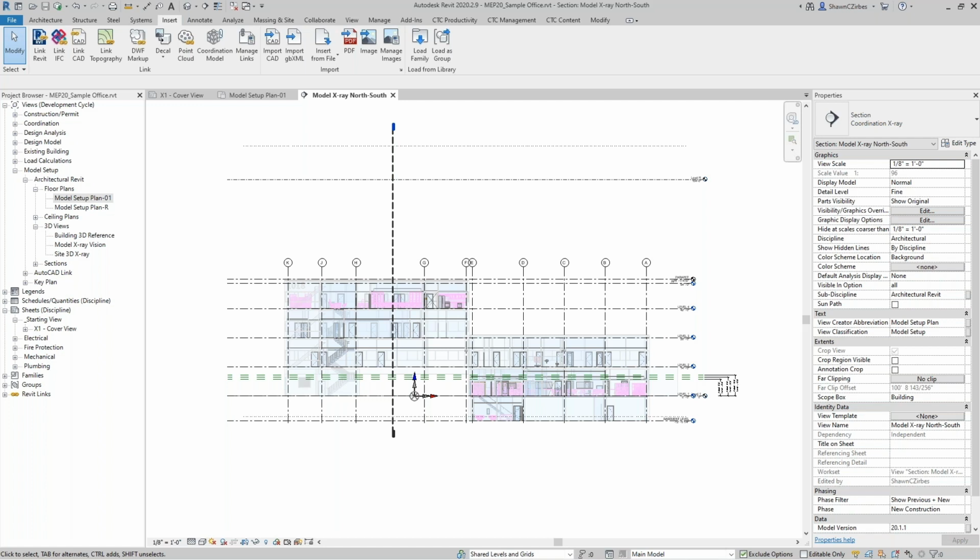So the documentation that originally came with the MEP Productivity Pack, and the one that's technically in the 20.1.1 release as well, indicates that we have 10 levels. And technically, you could. If you wanted to, you could have the 10-level workflow. If you started from the sample model, use our instructions to cut a new template. You could choose to not be as aggressive as we were with this template, and just don't delete the other 8 levels inside the building.